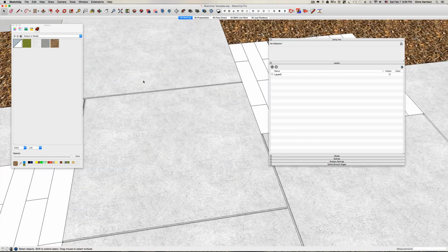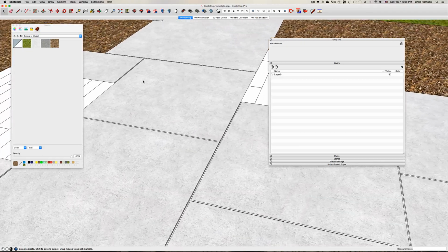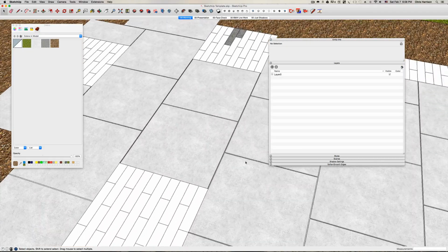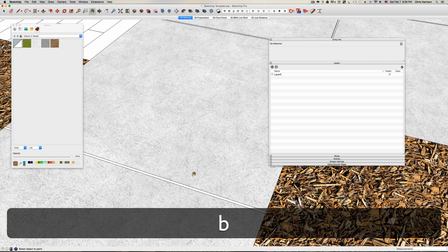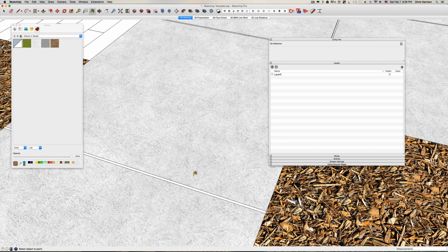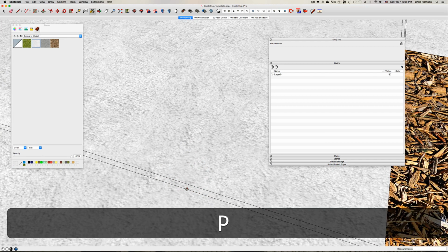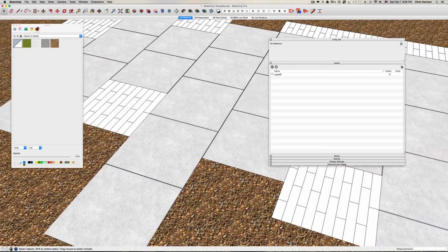Alright, that should have got that, yes. Oh, that didn't get it. I'm going to sample a color by using my Command on my Mac, and I believe Control on PC. And you'll see the eyedropper tool appear when you're on your paint bucket tool. And I'm just going to drop that color in because I missed it. And go back to my push pull tool and just recess that in half an inch.